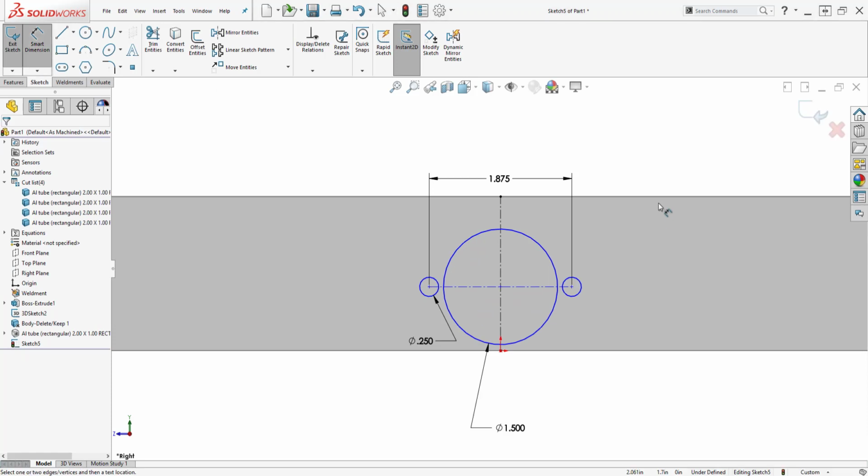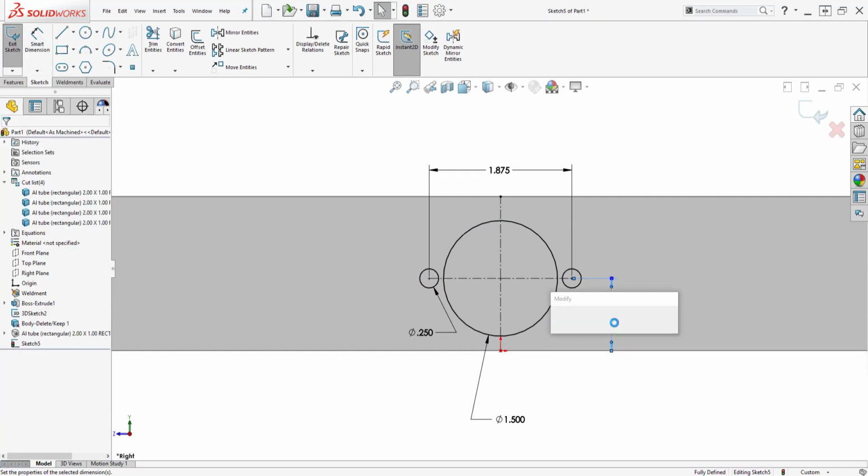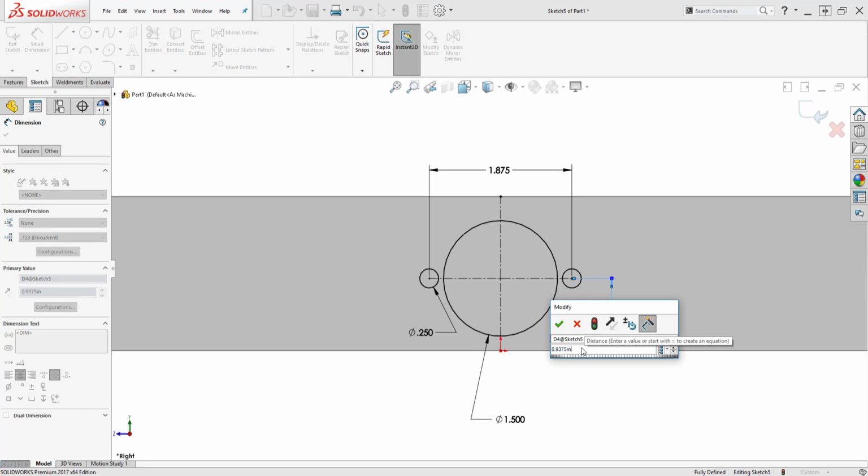For this hole pattern on the gearbox, this is the center. So I'm going to make this about 15/16 from the bottom edge, and this will be the final location for my gearbox to mount. The reason I'm doing it this way is so that this number is the same for the top and bottom. You'll just reference the top or bottom edge depending on which direction you're going with that 1/16 of an inch difference.